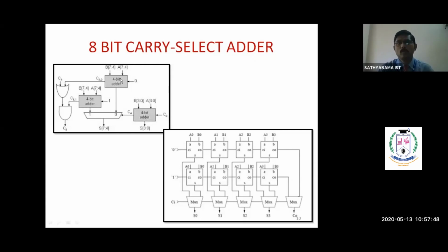So you may have a doubt. Here, for 8-bit addition, an 8-bit ripple carry adder is enough, but here we are using three ripple carry adders. In the case of VLSI, if you concentrate on speed, power and area, there is a trade-off between area and power, and between area and speed. So the area can increase, because we are concentrating only on the speed of computation.